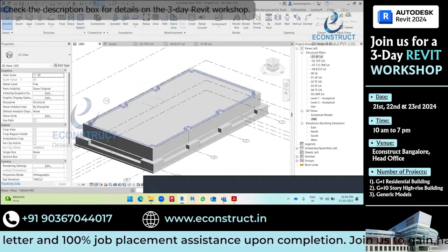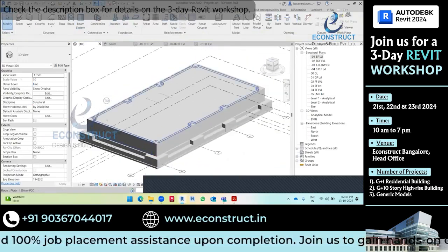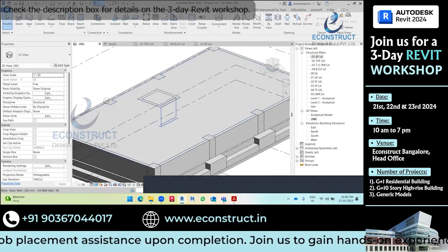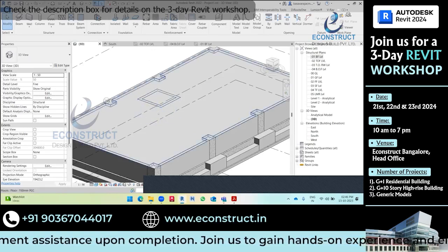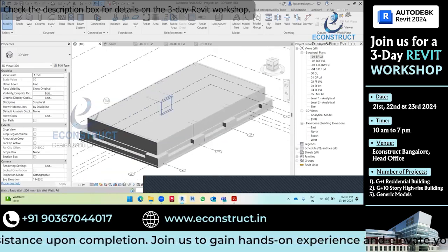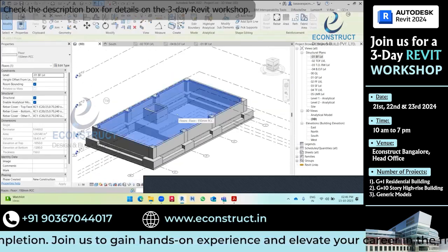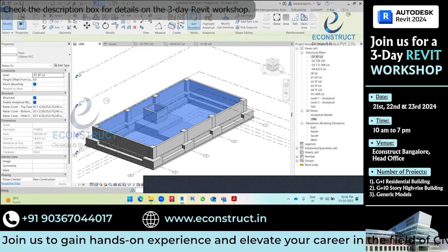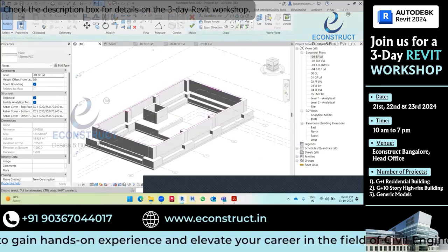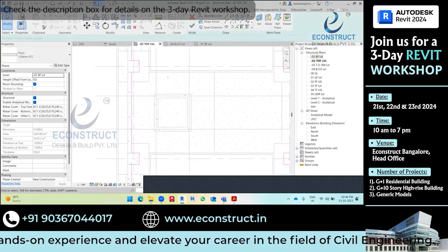See, now the floor has come, but we need an opening for this lift pit, right? So how to do that? We forgot to do the opening. Just select the floor and click on edit boundary, and go to that respective level.